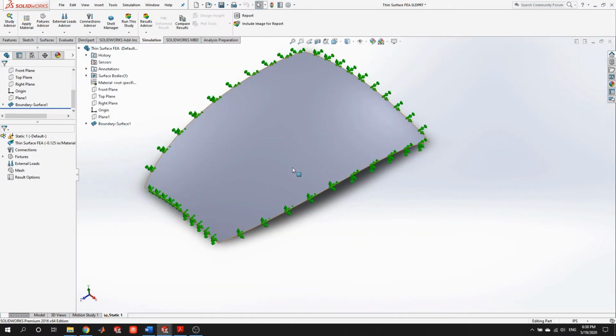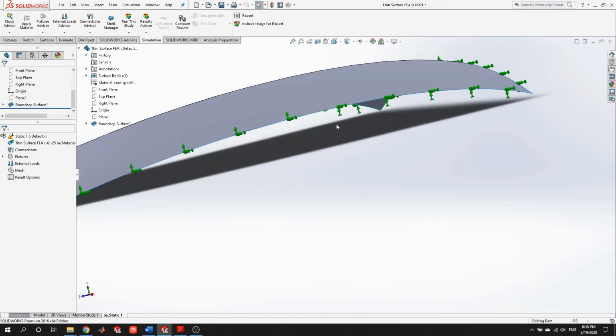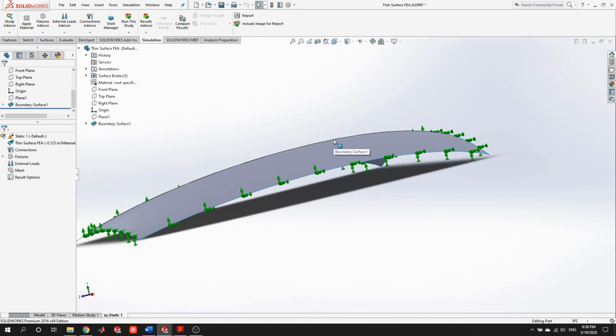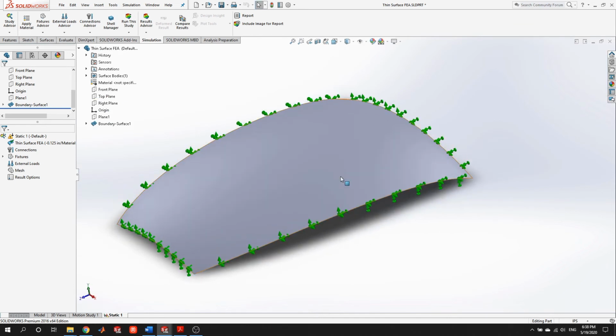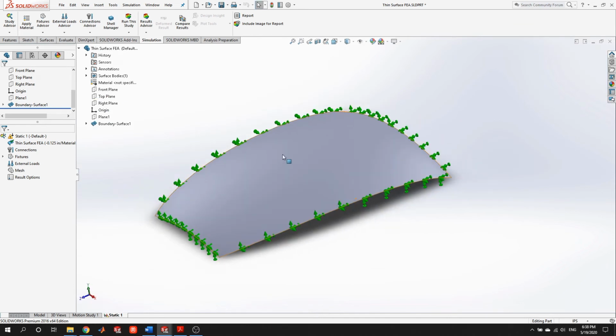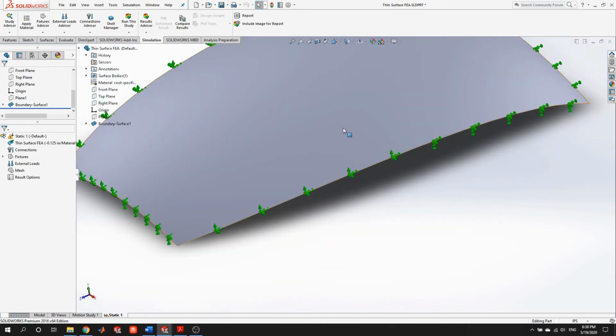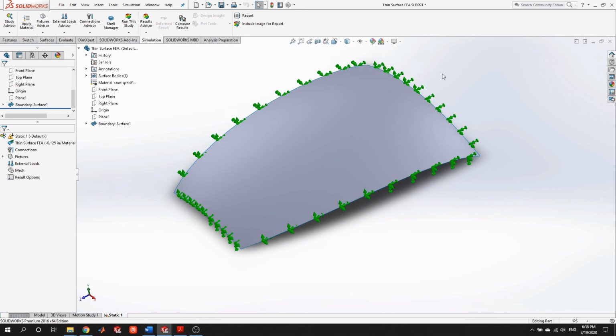Now we said that this is 10 inches. So we're putting a lot of elements along this direction that maybe don't need to be there to try to represent the thickness properly. If this is the case, there's another thing you can do. Another type of element that we can use is called a shell element. So what we're going to do is define the thickness in the program, and it's really going to apply elements just along the sheet and not represent that dimension. That dimension is going to be represented in the program, in the math.